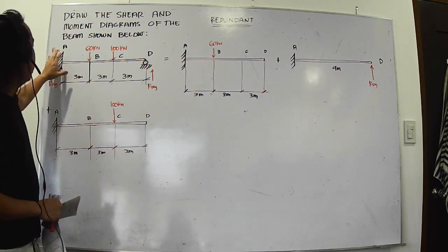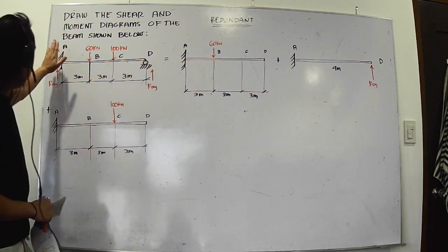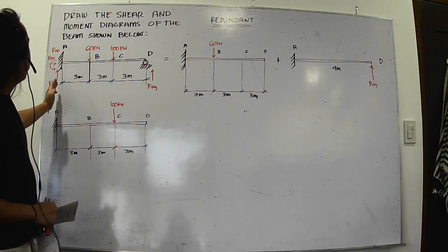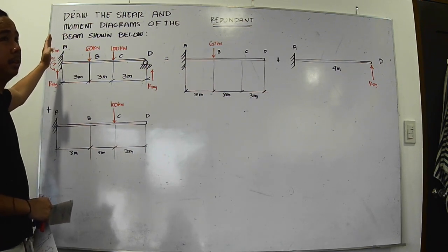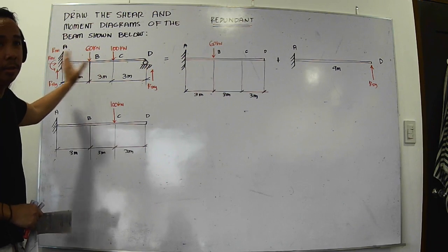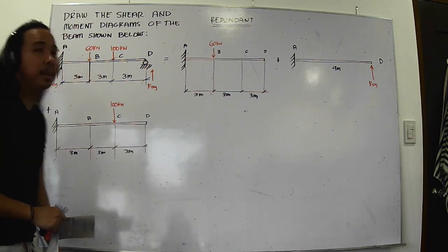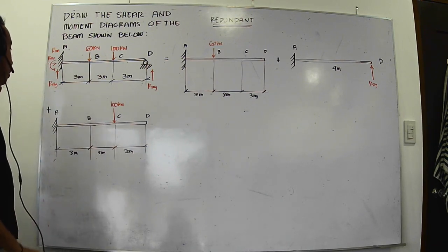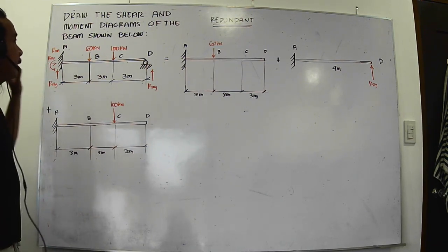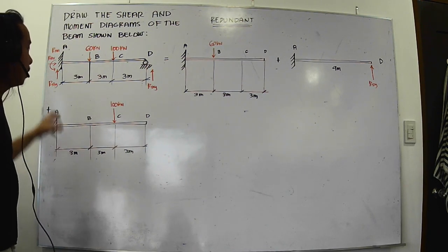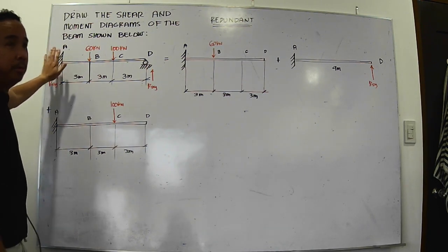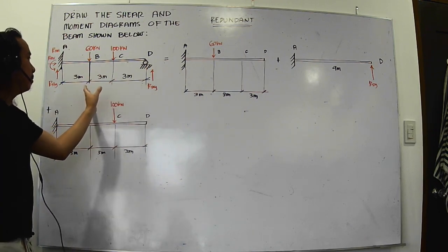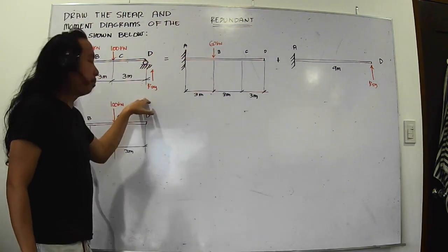As you can see here, even if we don't have the roller, this structure is still stable, because the fixed end prevents vertical equilibrium failure, prevents horizontal equilibrium failure, and of course there is the shear and the moment, which prevents rotation in our system. A structure is statically stable with three reactions, so this one is extra. It can be removed, so it is called a redundant support.